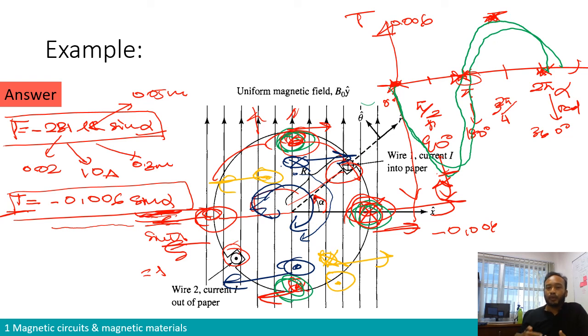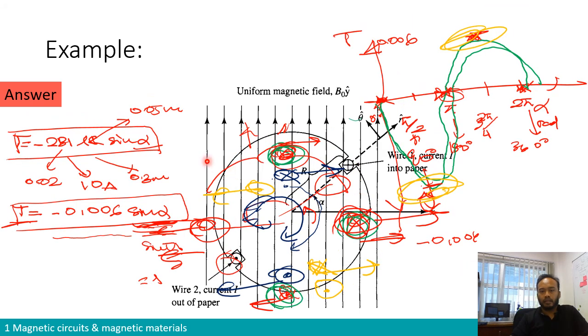So please try to do this exercise on your own, to make sure you understand the mechanism of the production of force and how to calculate the torque and identify the position in which we will obtain maximum or minimum torque. And we can see that the torque switches direction in function of alpha. So that's about it on calculation of forces, therefore torque, inside a machine using what we call the Lorentz force law.